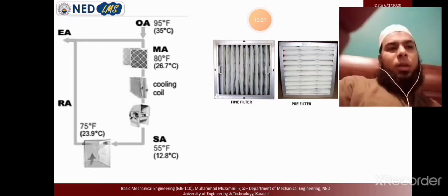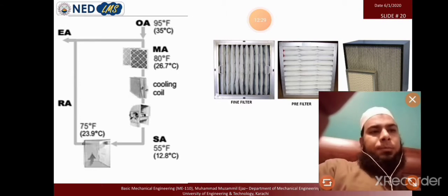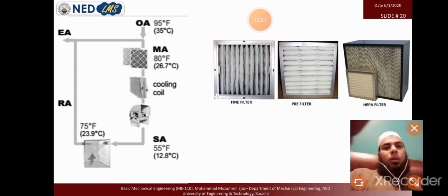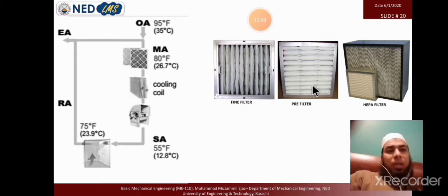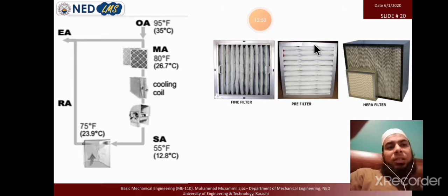Okay, now from the next picture, this is basically a schematic of the air side loop. This is the room. The blower supplies air, first taking the outside air, cleaned from the preheat, then through the filters. These are the pre-filters which clean the outside air. This is the fine filter, the back filter.